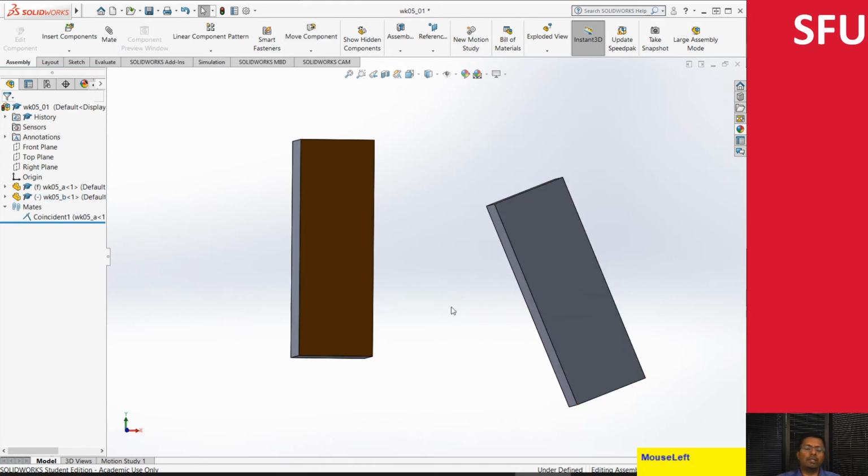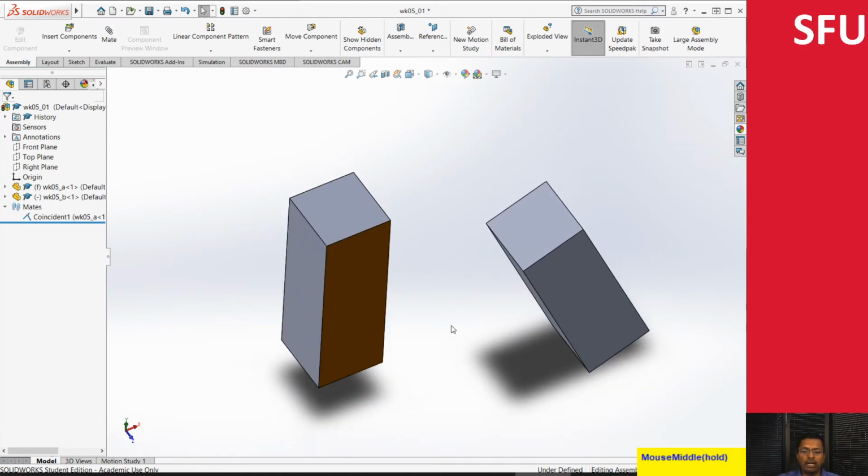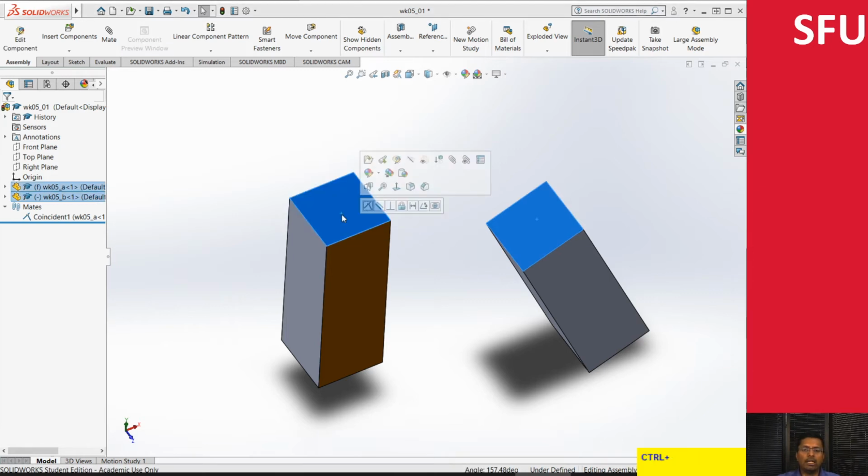So that basically means it's sliding all over the place, but it's still facing each other and it's mated on that face. We wanted to get an additional constraint, so we can look at the other constraint. Now I don't like these two being at an angle, so I can click on these, and then I can either make them parallel or make it parallel at a distance.